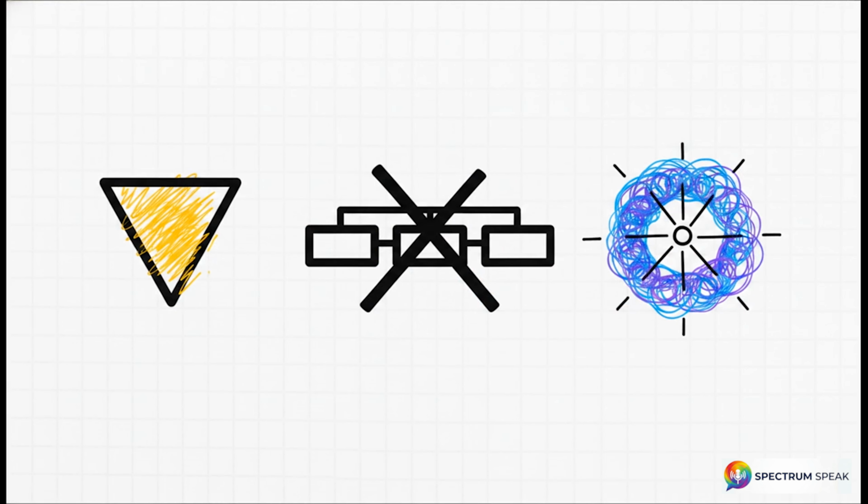All right, let's rapidly lock in the 3 most critical engineering takeaways from everything we've derived today. First up, ground is never truly 0 volts. Because every conductor has impedance, the golden rule V equals I times Z absolutely guarantees a voltage drop. Second, avoid daisy chains for mixed signals at all costs. As our math proved, they allow high-power motor drivers to completely ruin the ground reference of your sensitive sensors. And third, watch your frequencies. Stray capacitance limits the effectiveness of single-point grounds to under 100 kilohertz. Above that, you really must transition to a multi-point ground plane system.